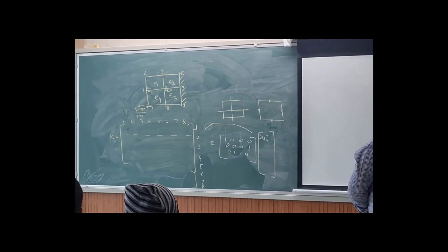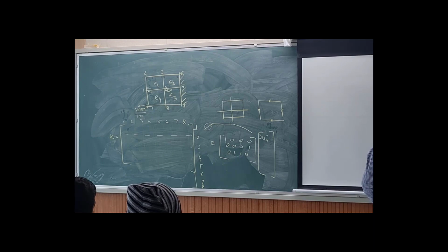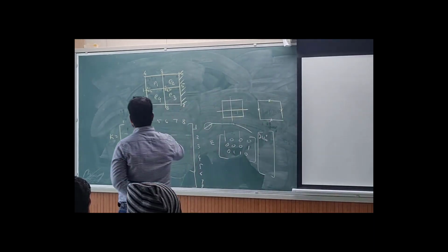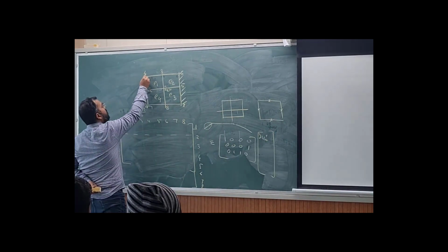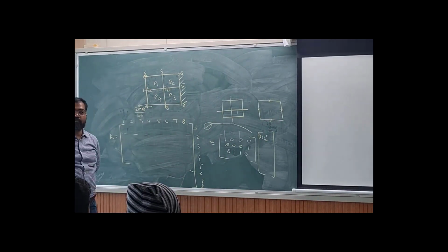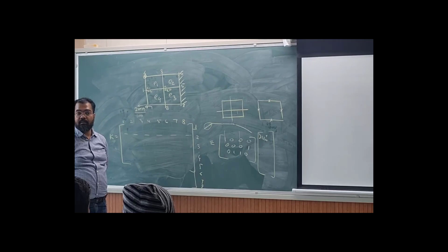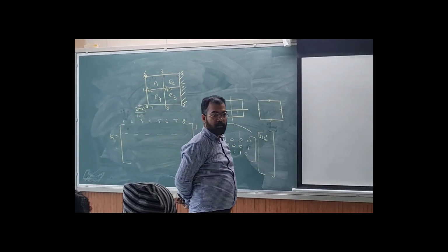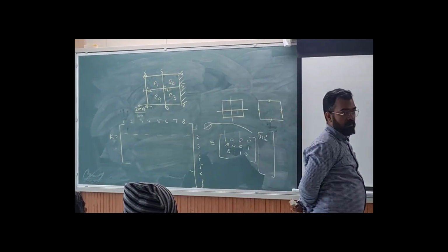I will have the summation of all the K21s which I am getting from the locals, and I will add them. K41 and K42, for instance, will have no contribution from any other element, so they will be untouched. And by assembling these, I will make the global stiffness matrix.